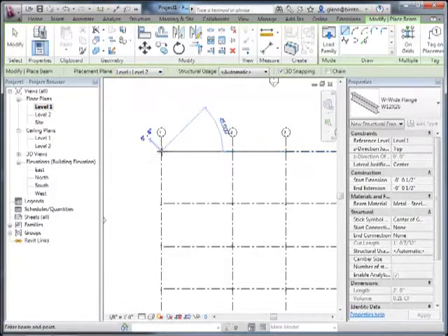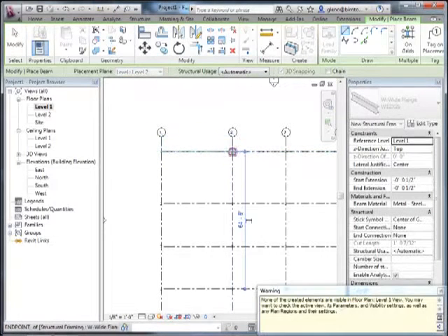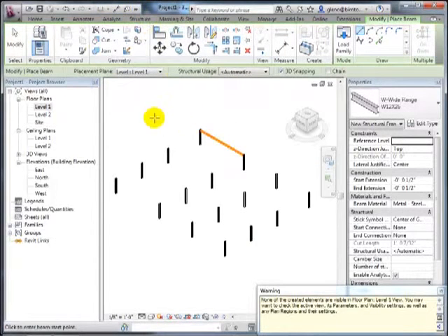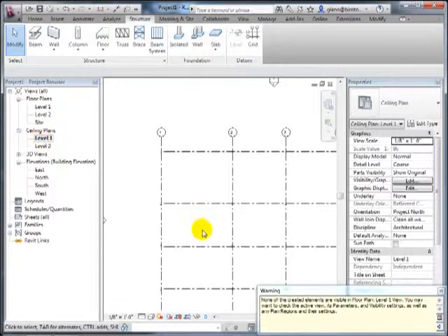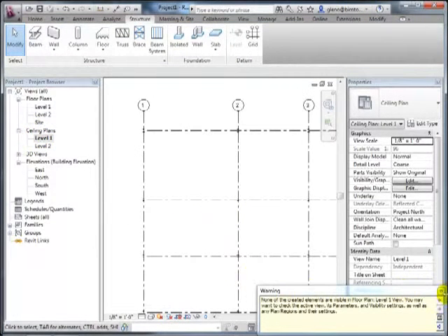And as I go clicking here to here, everything seems to be okay, but I get this little warning that says it's just not visible in this view. And it's trying to warn you, you are creating things, you just can't see them right now. And that's because it's above my head. Again, if I would go to the 3D view, you'd see it. Okay, there it is. Or if I go to the ceiling plan view, I can see it there. Or I could almost see it there. I don't quite see it there.